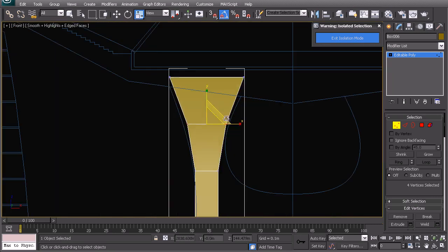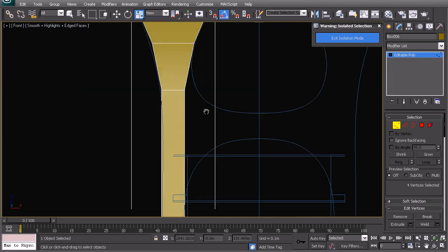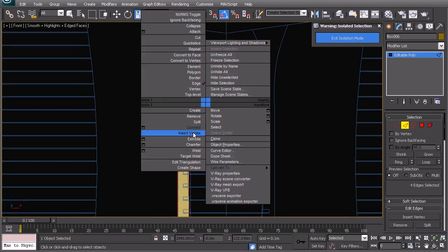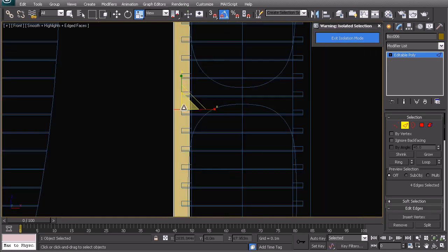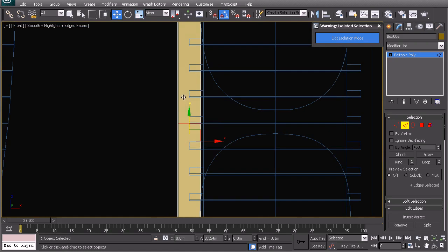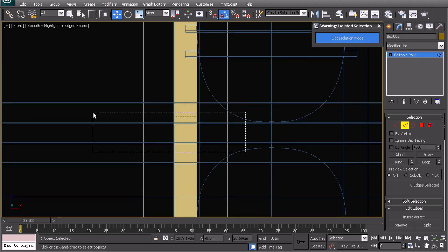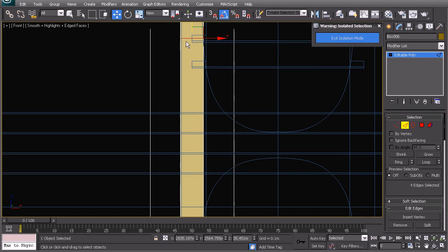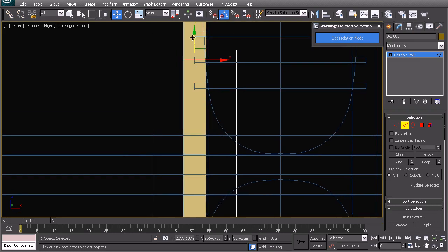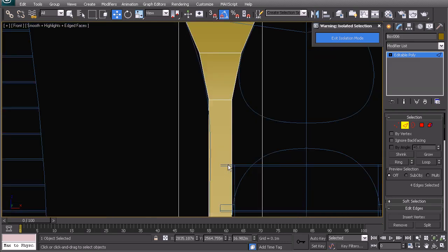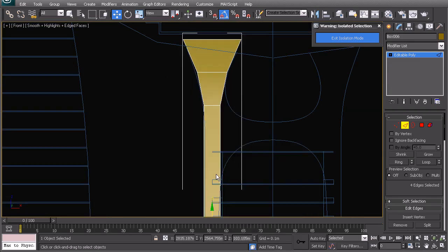We're going to do the same thing here. I'm going to keep looking in the front elevation so that I can get the main scale to look correct. And once that is done, I'm going to connect again. And here I'm going to drag these lines roughly to the middle of these connecting webs that we have here. I'm going to do the same thing here. Right click and connect. Drag that down, just visually placing it in the right place. And the same thing here for the last time.